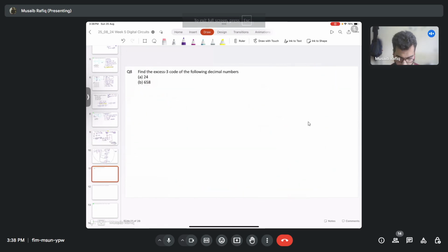This was question number 7. Question number 8 of today's live session. We have to find the excess-3 code of decimal numbers 24 and 658. So the excess-3 code of 24: let's write the BCD of it. It will be 0010 0100.